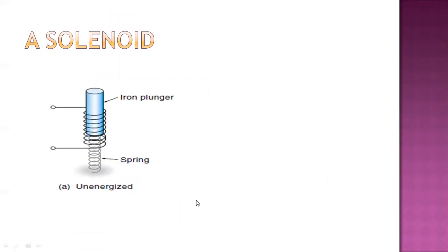Here you can find the coil which is used. It will have some voltage or current rating and may be DC or AC. The solenoid specifications include the electrical rating and the plunger pull or push force when excited by a specified voltage. This force may be expressed in newtons or kilograms in the SI system and in pounds or ounces in the English system.